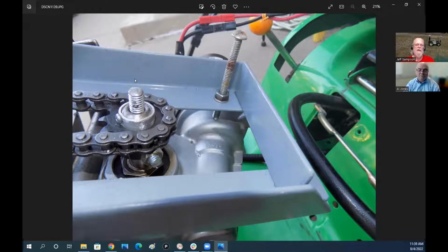I can either pull this bolt out and then drill and tap the side of a pot and stick it down in there directly, or I can put a coupling. I had a misalignment coupling on here, and I dropped it a couple of times, so I smashed it up enough that it's not going to work. So I just have to figure out some way to get a pot onto this motor, and then I can basically turn the motor into a big RC servo by putting a little bit of software that drives that driver board and then drives the motor. So that hopefully will take care of that. And then I probably don't have any pictures here. Let me back up and see if I can find that one.